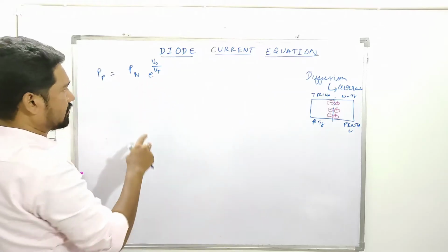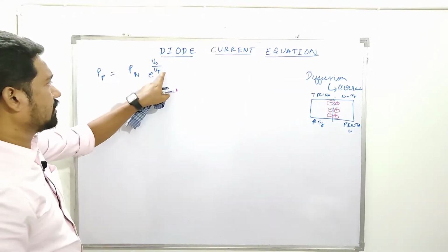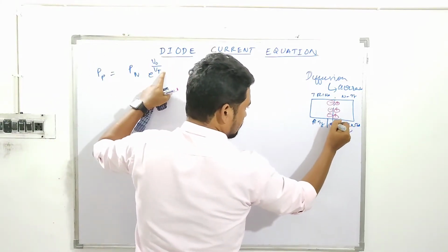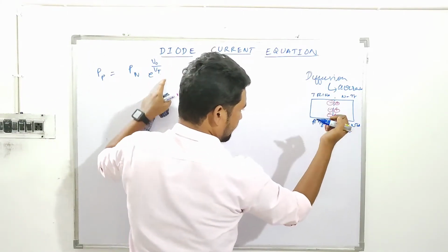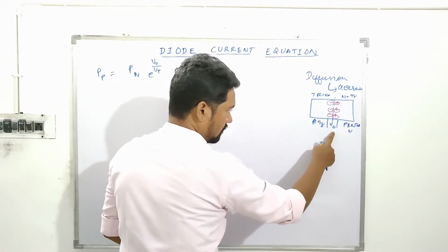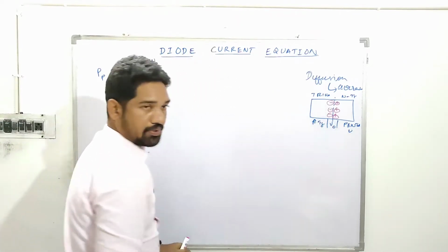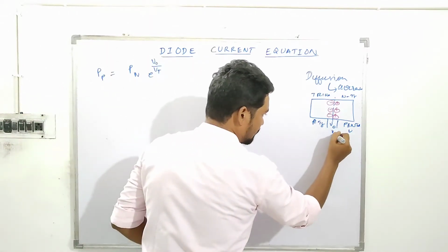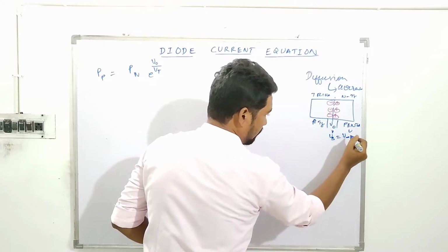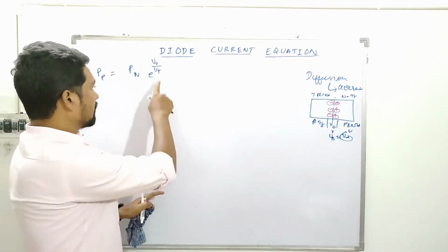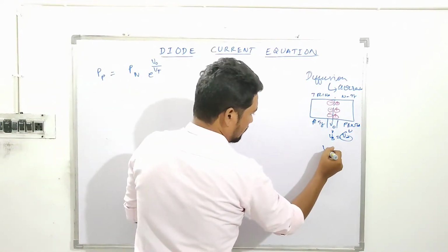And now we have to have clarity of what is that V0 and Vt. V0 is the barrier voltage, this one. V0 specifically, why? Because it's open circuit. We haven't biased that one. All right. So V0 is for the diode under open circuit. The barrier voltage, some textbooks say it's VB, which is equal to V0. Why V0? Saying that it's under open circuit. All right. Now this VT.